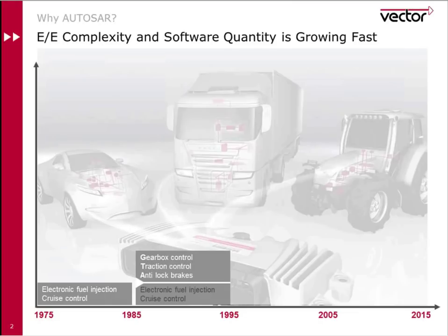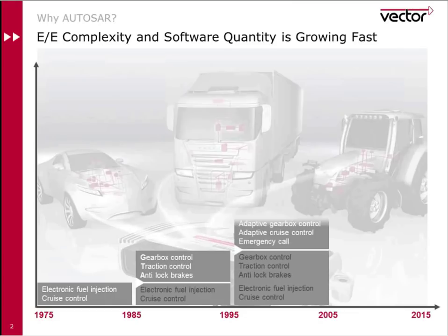Nowadays, we see multiple CAN networks, perhaps 5 or 6 CAN networks on the bus, with many, many ECUs all sharing data between them. And these ECUs can take advantage of the data that's effectively public data published onto these buses to provide new features and new functions. So whereas before we had cruise control, perhaps now there's radar information on the bus, and just as a software function alone, you might be able to implement something like adaptive cruise control.